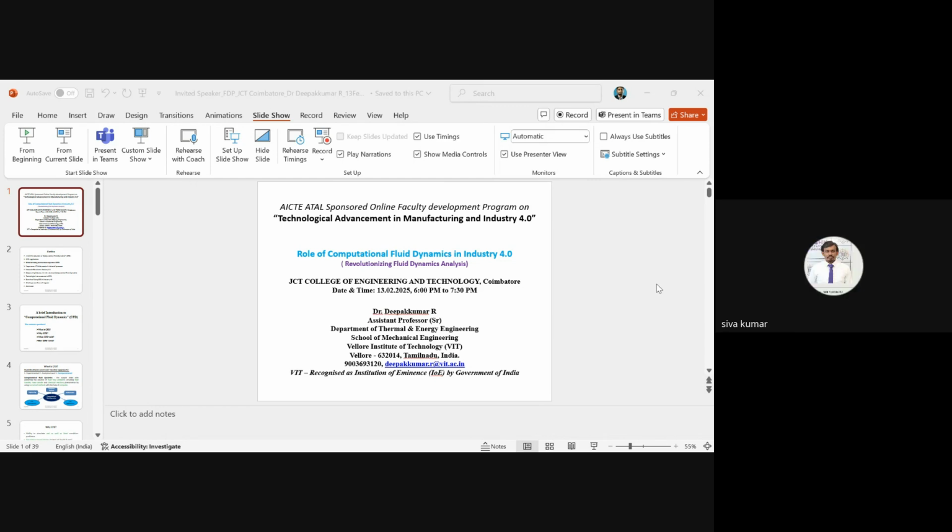Yes. So is anything correlated with the welding process the reason for this erosion? Only the welding zone is affected more. Yeah, that's what I'm asking. Corrosion is something different, erosion is something different. Corrosion, that physics is something different. Now if you are focusing only on erosion, you have to focus only on the skin friction coefficient of the material. That skin friction coefficient is predictable by the CFD software.